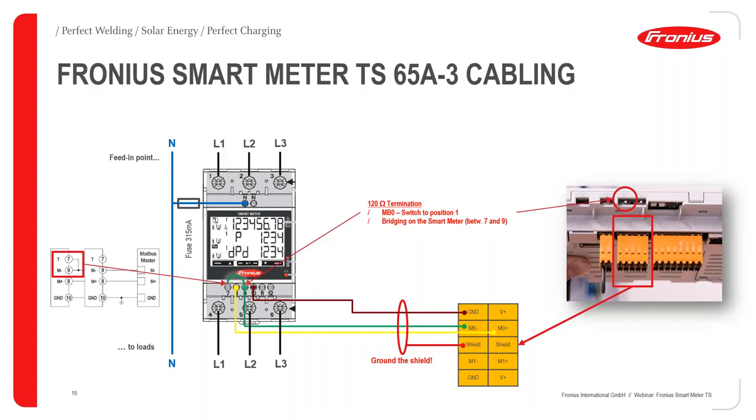And the third one is not listed here, but on the next slide. Always use a twisted cable pair between data plus and data minus. For that, we recommend using a Cat5 cable or a higher standard, because they already have these twisted cable pairs inside.